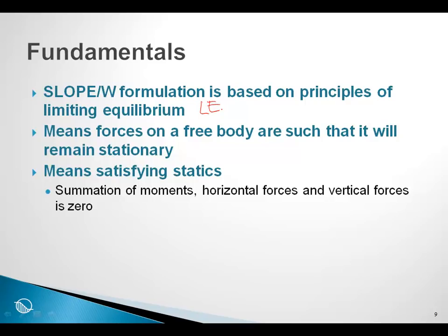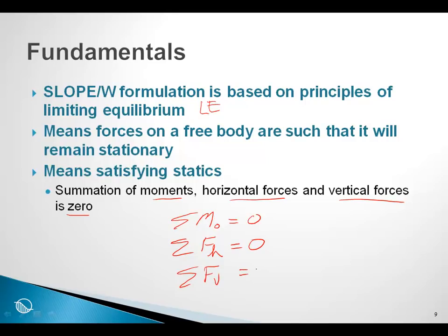It means the summation of moments, horizontal forces, and vertical forces must be zero. So the summation of moments about some point must be zero. The summation of forces in the horizontal direction must be zero, and the summation of forces in the vertical direction must be zero. This is at the heart of a limit equilibrium formulation.